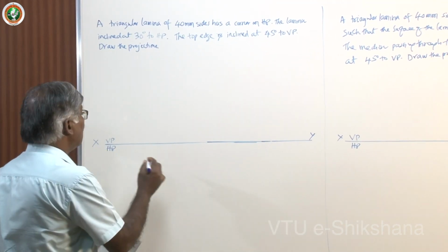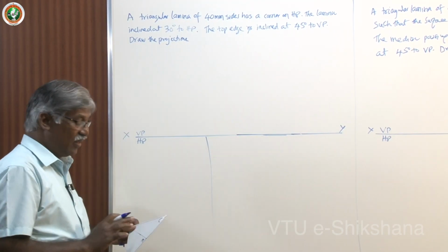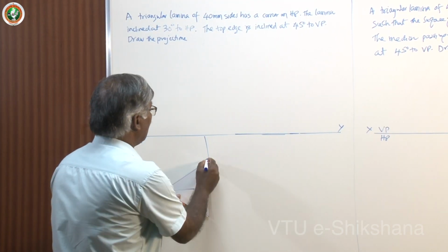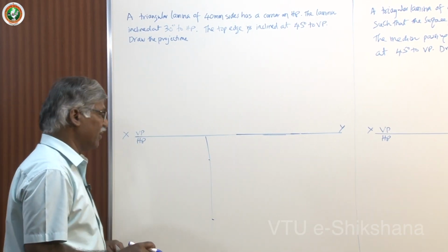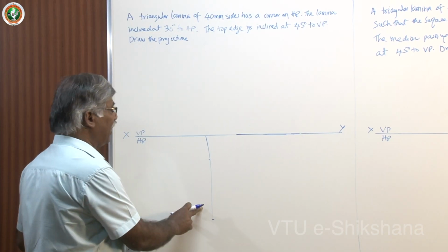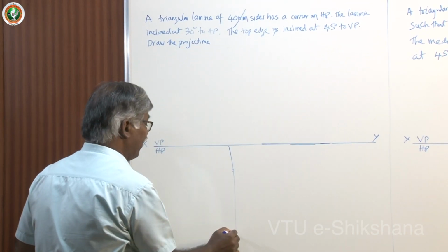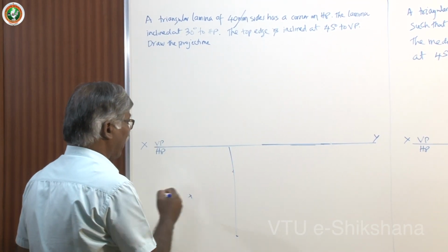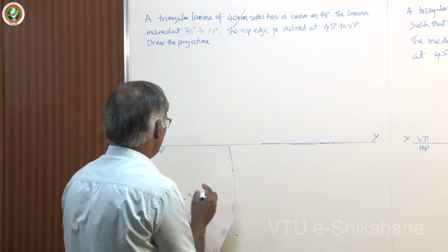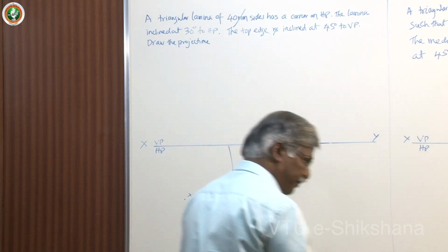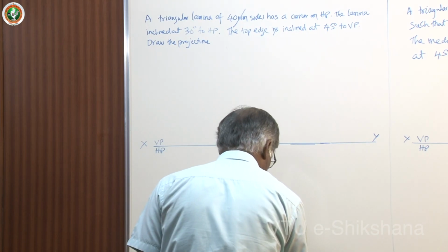As I said, instead of starting from the corner, start from this, the pentagon and triangle and all; you must keep it like this. Then assume that I have created it. You know how to create the triangle. I will show you how to create it in the computer, but manually, you measure 30 mm or 40 mm, whatever is given, and then take the same distance equal to radius and draw two arcs. Definitely you will get the corner. Now see this, I am keeping this. So straight away you can draw dark lines.